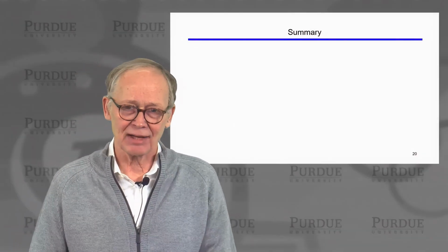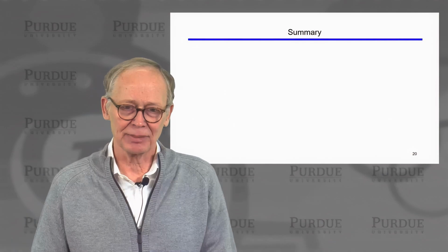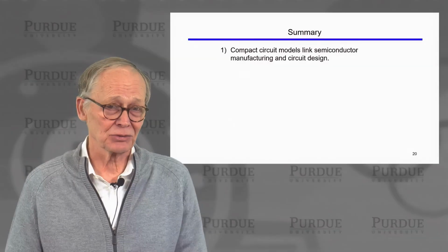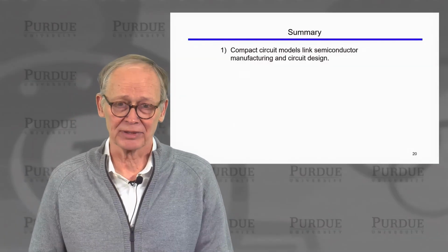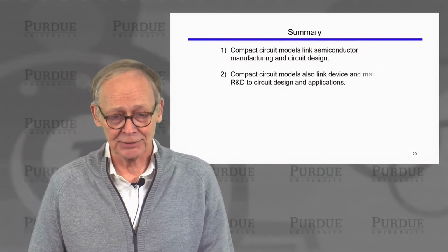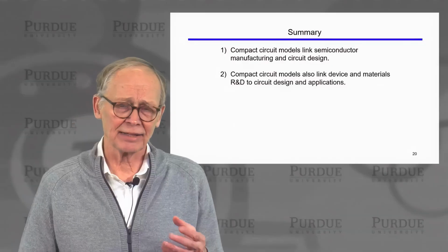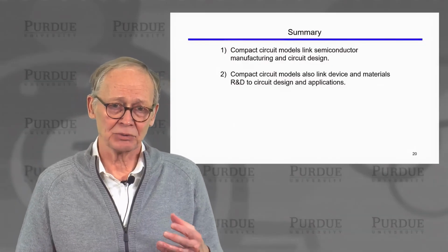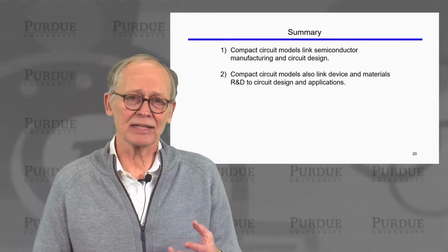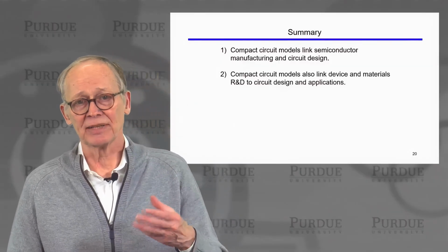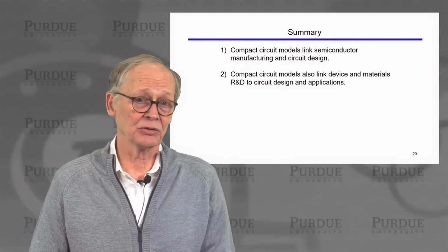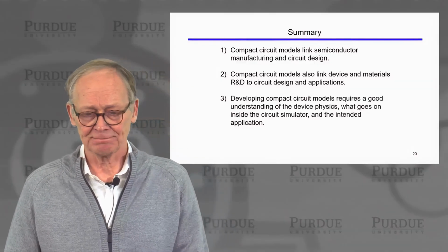Okay, so with that, I'll wrap up this very quick tour of compact models. Just wanted to make you aware of a few considerations should you need to use or even develop your own compact model for circuit simulation. They are the link between the manufacturing process and the circuit designer. They also are an increasingly important link in research because research on novel devices needs to be driven by the impact on an application. So at an early stage in your device development, you need to be thinking about what are the implications on circuits and systems. And for that, you can make use of less sophisticated compact circuit models.